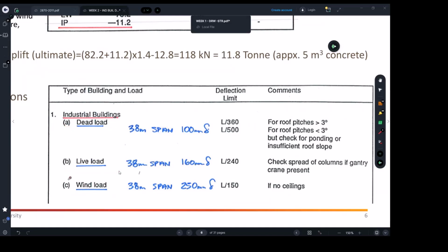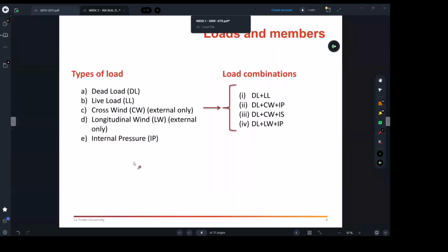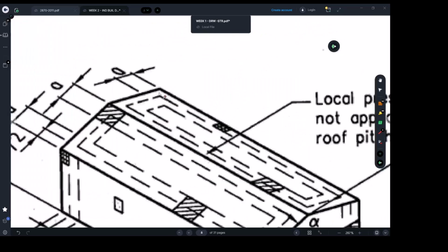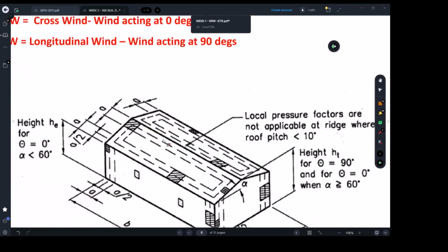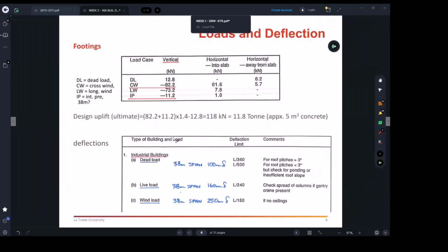Live load, if you maybe start placing furniture or talking about a warehouse, if you start putting some chillers, like you have some air conditioning units placed on one side of your warehouse, right? You start putting in the back here some chillers, some air conditioning units here and there, and then you have to do that check, making sure the beams have not deflected a lot and they are still within acceptable limits. Like here, that's where you use such documents.